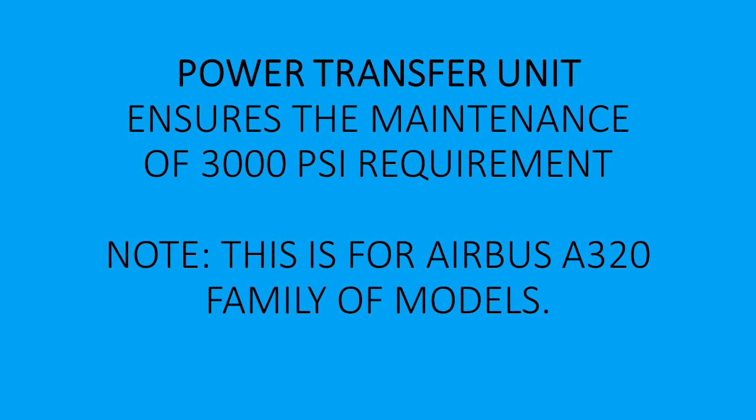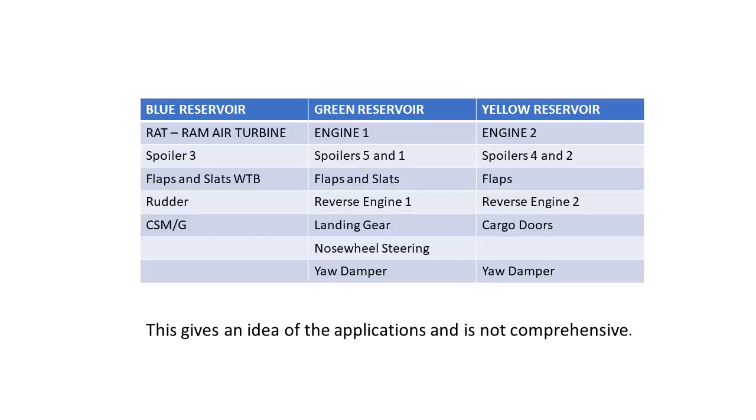And then you can just get a feel for the orientation of the applications that the green hydraulic system provides that hydraulic pressure to. The diagram shows at the top left, you'll see that you have the yaw damper, pitch trim, rudder, and an elevator. Okay, you got slats, ailerons. This is on the left side, left hand. Spoiler 5 and spoiler 1. And then kind of center, you'll see also right hand slat and the ailerons, and then spoiler 5 and 1 right hand. And then also the nose landing gear doors, so it supplies pressure to there for that actuation.